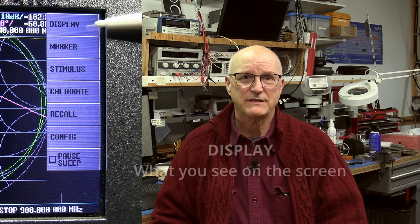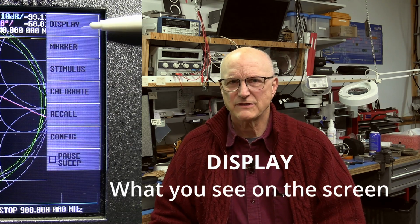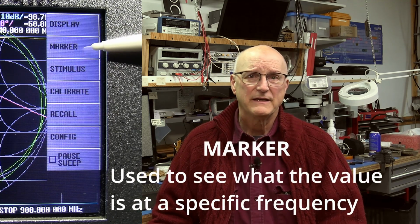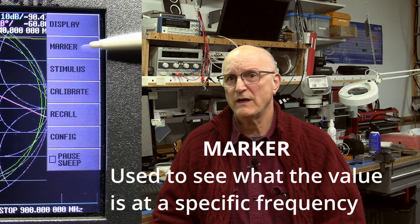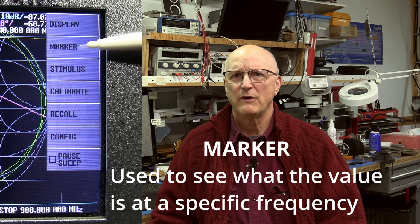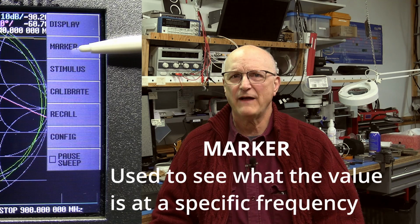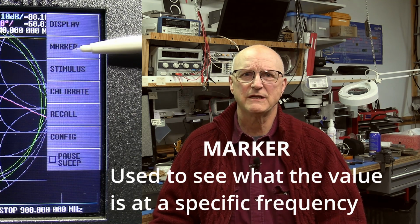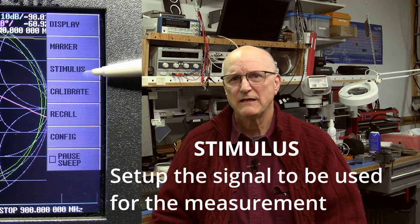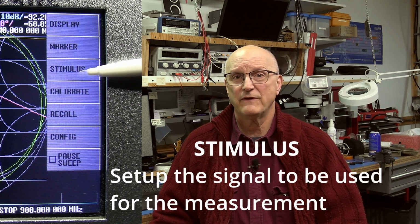Starting from the top, we see Display. This is where we go to set up what we see on the screen. Marker is where we set up markers that we can move across the screen once a measurement is made. We move a marker to a frequency of interest and the nanoVNA will display the value of the measurement at that frequency.